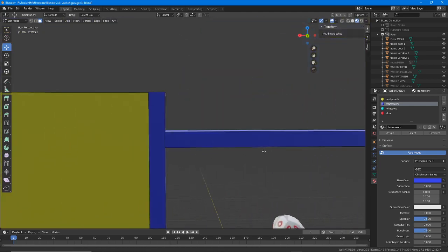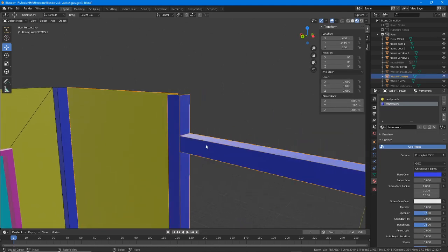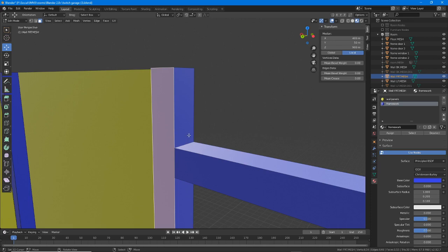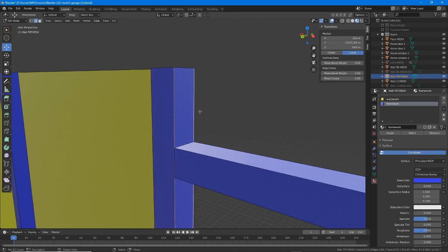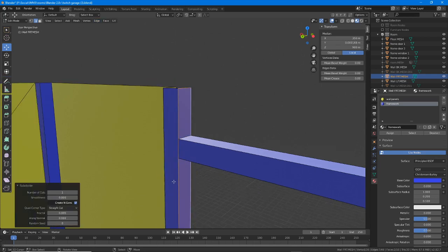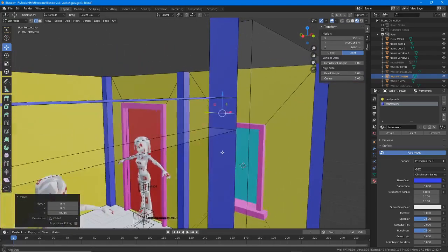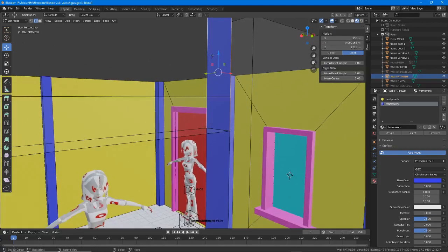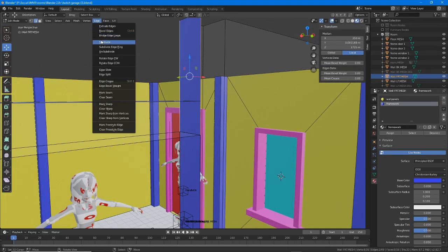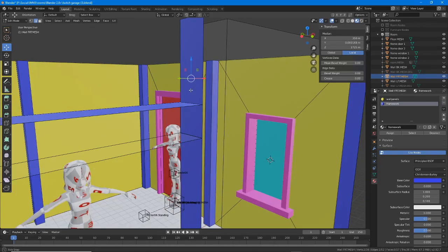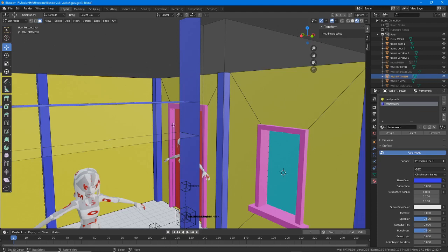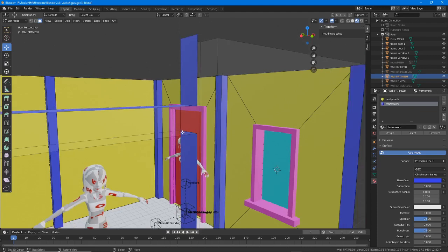And we want to do the same thing on this pillar, but that's part of the section that we were just editing. So edge, subdivide, move that into position. Select that edge, subdivide. So instead, because we know that's 1650, we can just select it, type 1650, drops it into place, get rid of that face.